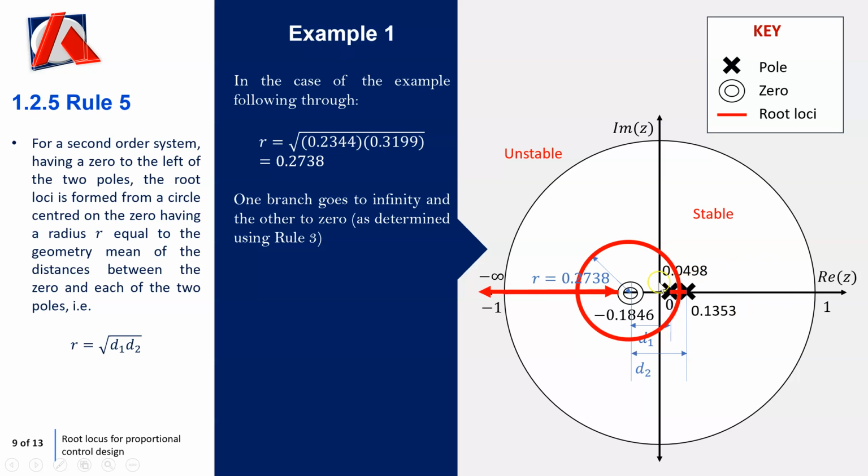Because if you recall, you have lines of damping ratio and lines of natural frequency. As you change your Kp, your pole location changes, and that relates to natural frequency and damping ratio, i.e. it is going to give you different system performance.